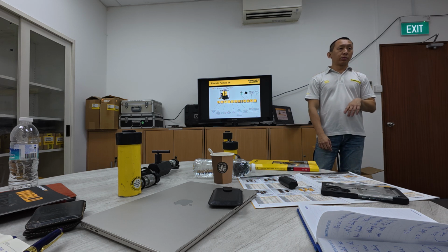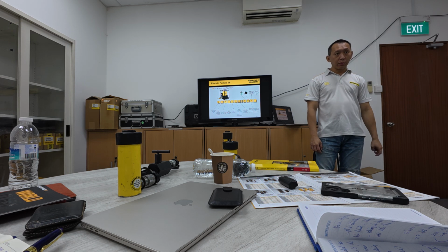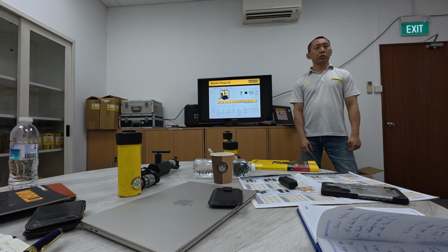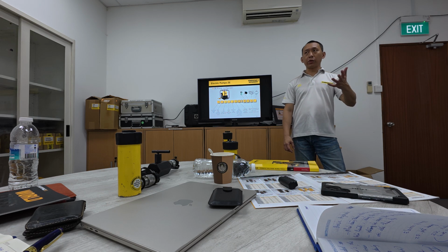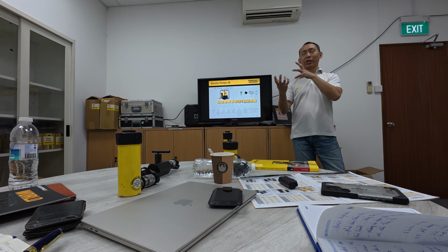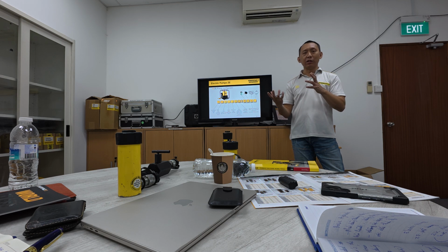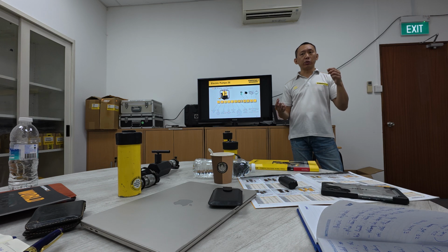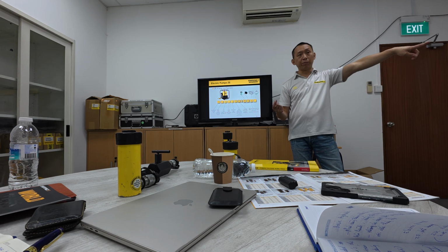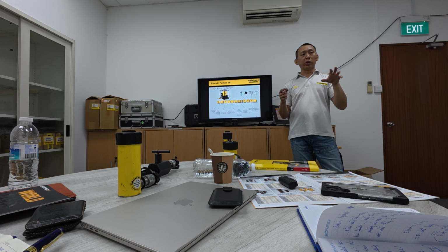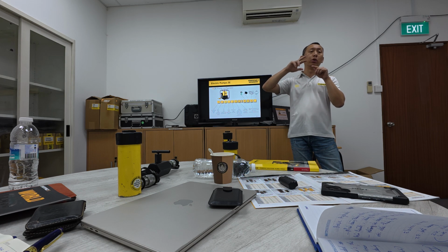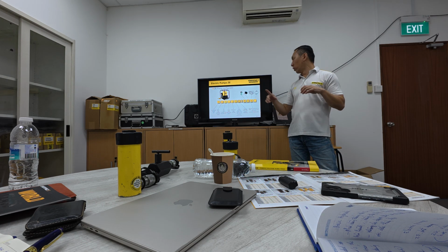Or we can use pressure meters outside of the pump. Yes, you can. You can also replace the pressure transducer with analog for saving money. It can be done, just that the transducer gives you more options. Because the transducer connects to the panel, it allows you to have settings. You can set settings on the transducer, so you can have automatic mode on the pump if you have the transducer option.